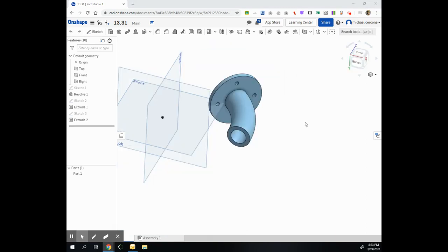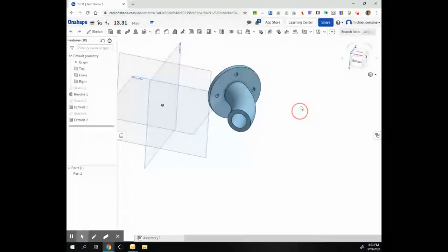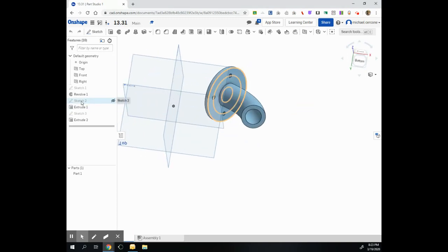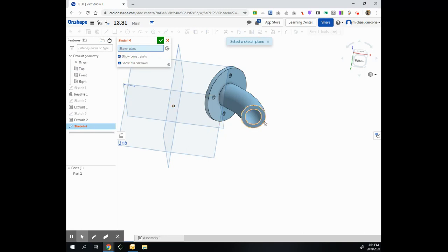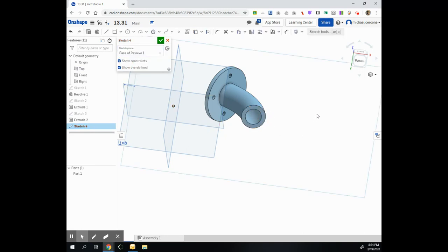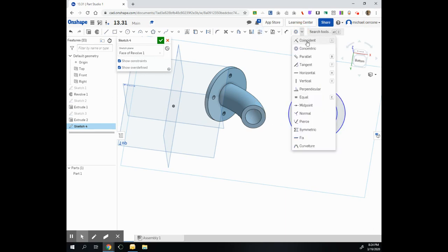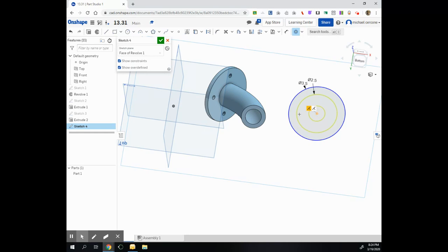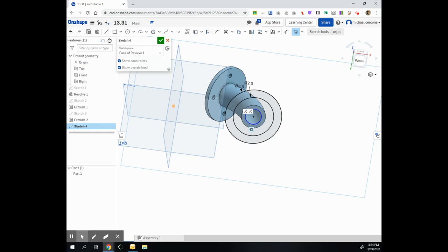Just like on SolidWorks, it is possible to copy sketches as well. So what I'm going to do is just select Sketch 2, choose Copy Sketch. Now I could start my new sketch, showing my constraints on Sketch 4, or Sketch 4 on the surface, and then paste sketch entities. It's just going to paste it pretty much wherever I drop this. And now I could move these into place, or I could apply relations to move everything into place.